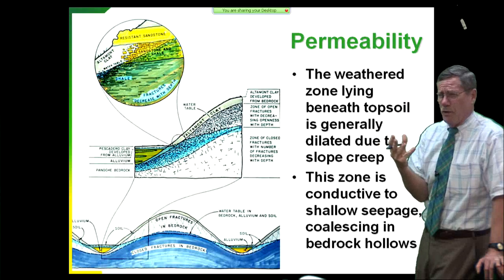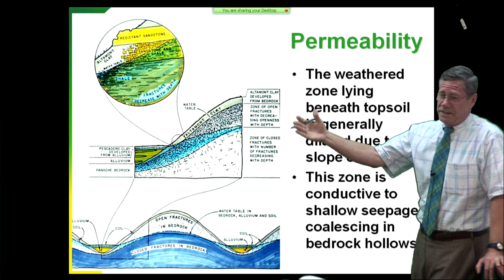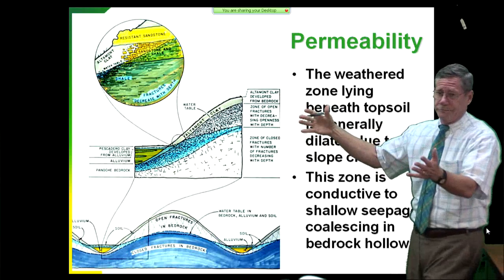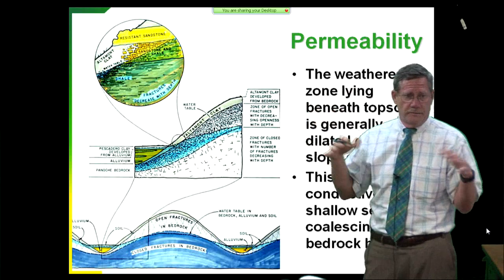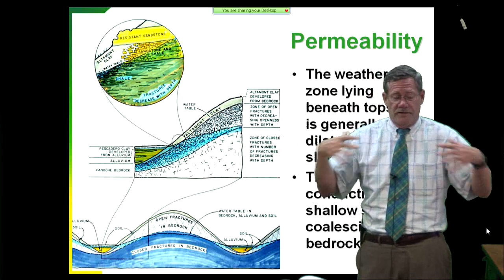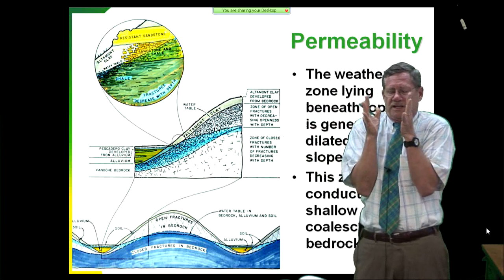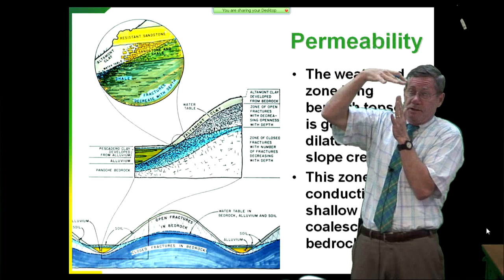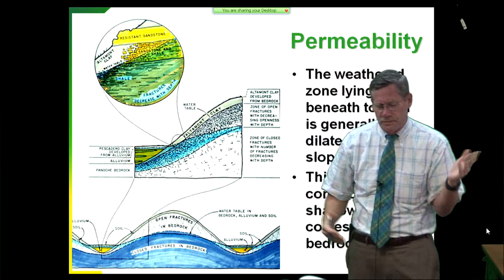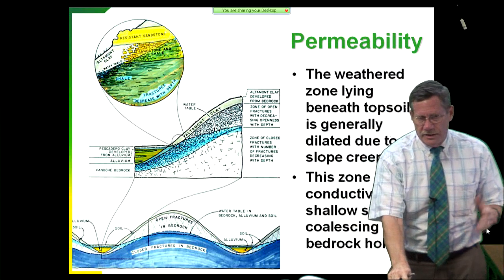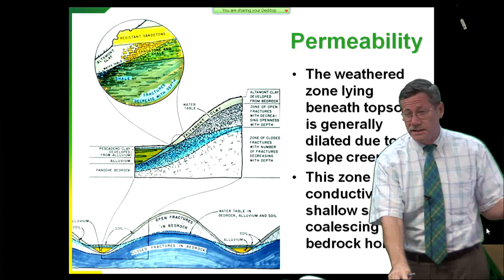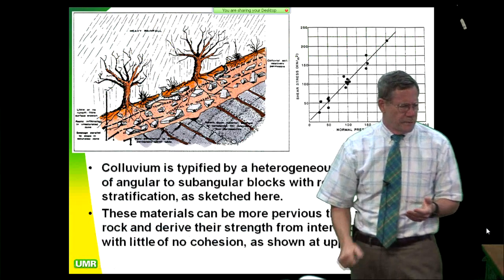If you have that same storm hit at the end of the wet season, you'll get a record flood because you have high runoff coefficient, because after you've taken all this water in, the desiccation cracks swell closed. So now when additional rain comes, it just sheets off as runoff. So the runoff you get depends on the 60-day antecedent moisture.